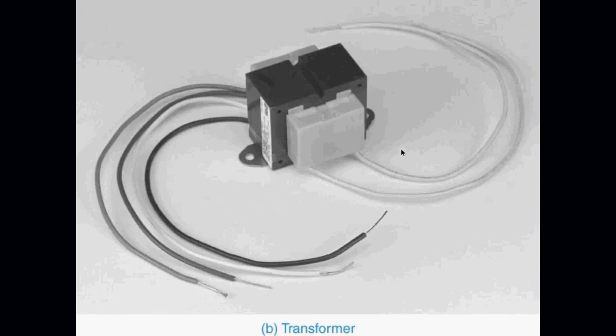And this is just an example of a multi-tap transformer. I have my two secondary wires coming out of here. Unfortunately, these are the same color, but it's AC circuits. Does it really matter? No. One of these wires on the other side, probably the white, is going to be common. One is going to be for the 120 volt, one is going to be for the 240, and one will be for the 208. And they're all different colors. This just happens to be a black and white picture.